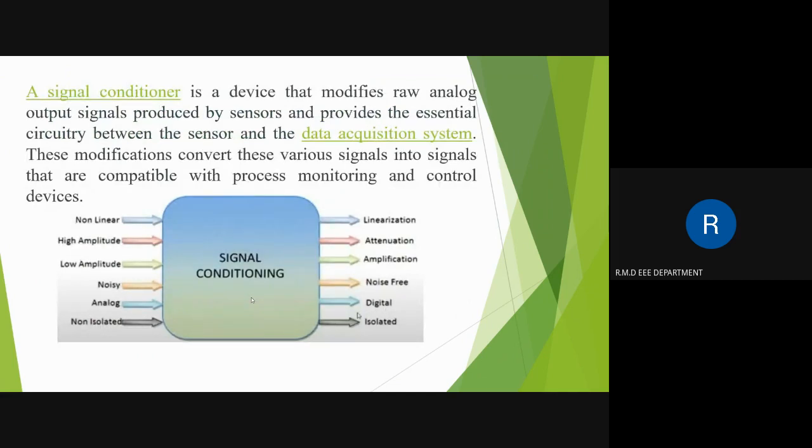The amplification system brings the level of the transducer signal to a value which is enough to make it useful for conversion, processing, indicating and recording. Modification or modulation means the change of the signal in a manner such that it is smoothed, linearized, filtered, or converted into digital form. All this comes under modification.